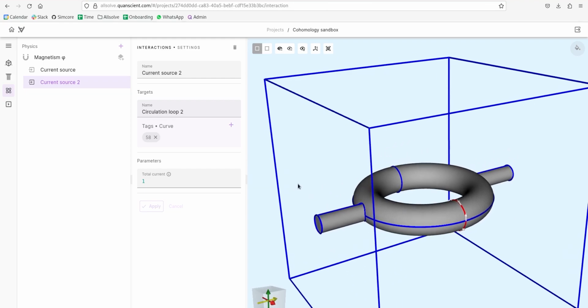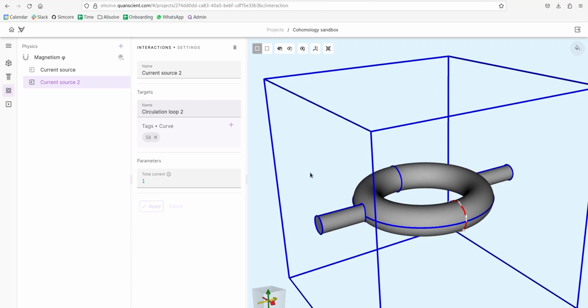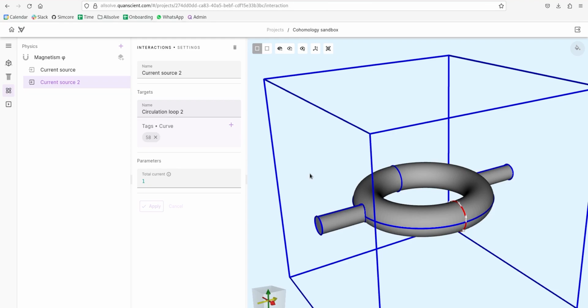So you can really define, based on circulation, how much total current flows at each part of your geometry, and the amount of equations that you have to provide is entirely defined by the topology of your geometry. If you have 1 conductor flowing in air, then you just need 1 circulation because you entirely define the system with only 1 equation. In this case, if you think physically, you will realize that you need 2 constraints so that all the currents everywhere are properly defined.